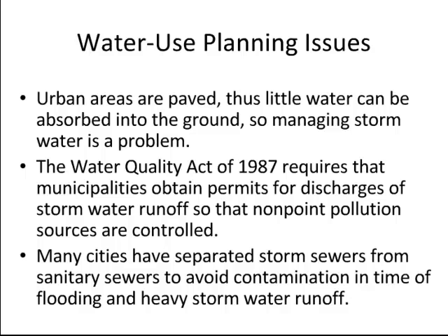So in terms of artificial swamp areas, it's a win-win situation for a municipality. Not only does the swamp improve the water quality of that water that ends up in the river, it also increases the amount of infiltration and therefore increases the groundwater available to the municipality. And third, it decreases the likelihood of downstream flooding, because the swamp can act like a big sponge and soak up large amounts of water. It mitigates this peak and trough idea of water flowing quickly when it rains into the river and then there being no water left to fill the river during dry times.